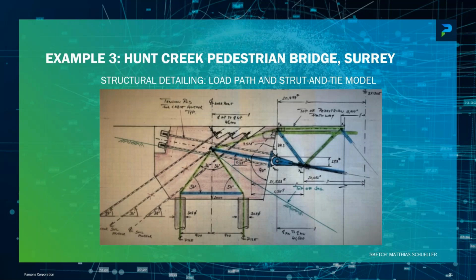And when the truss is established and you add additional loads like live load, then you see that you actually have a negative moment capacity at the abutments, because you have a lever arm there, and that gives you a very stiff structure. But for temperature effects, the structure is still very soft because we had a little bit of bow in the deck, so it can breathe again. And for seismic, it's also very, very stiff laterally and longitudinally because of the rock anchors.